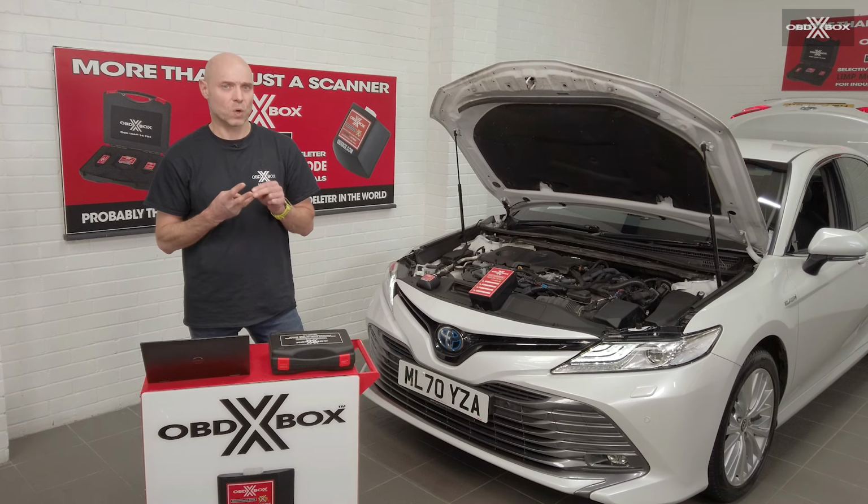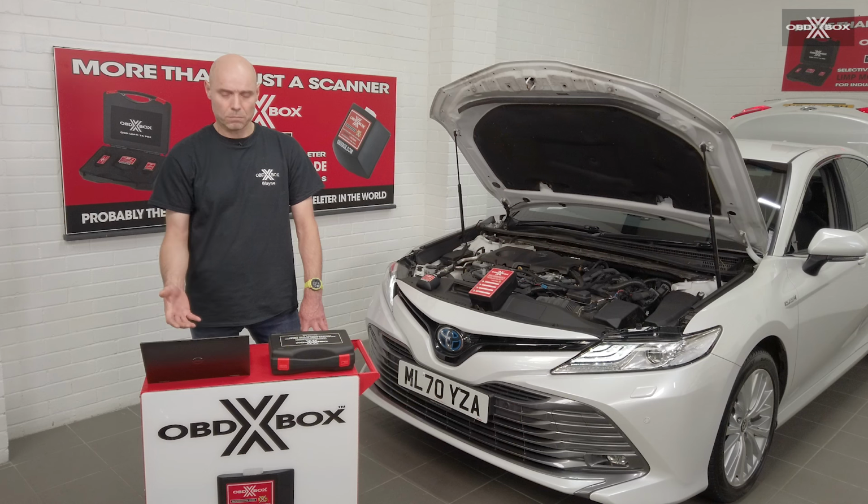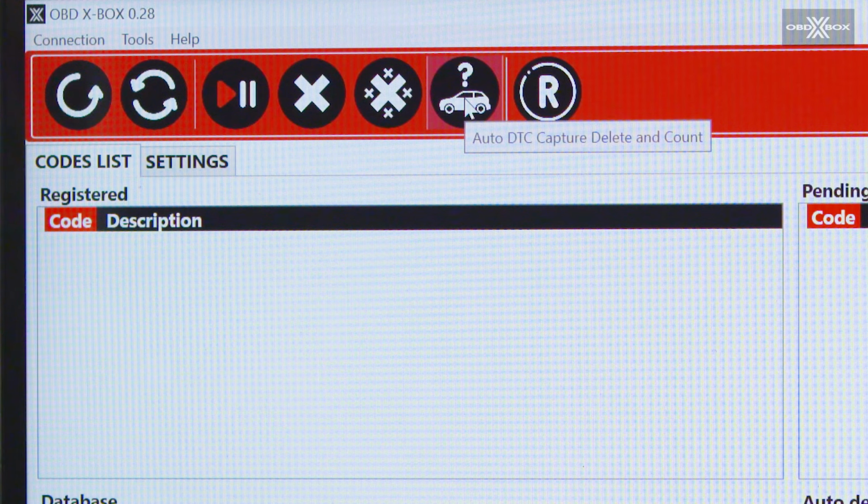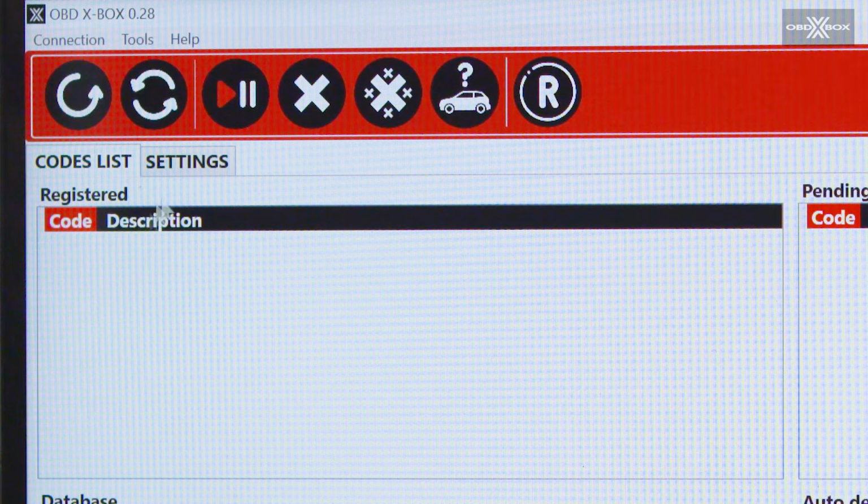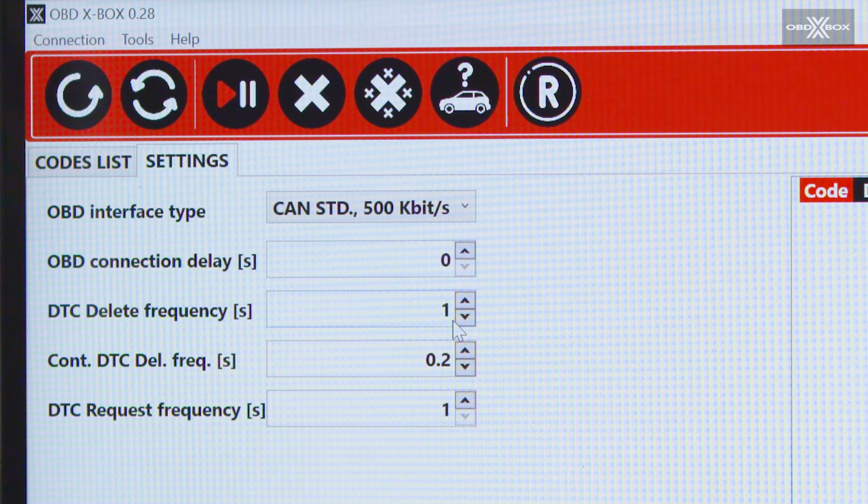So to be able to continuously identify fault codes coming up, select them for auto deleting and delete them, and then study the frequency of the codes coming up, it gives a much better understanding of what is really at fault, because it's not always the first fault that comes up. There's a minimum time setting of 5 seconds. That allows codes which may ordinarily be missed to come through and be caught.